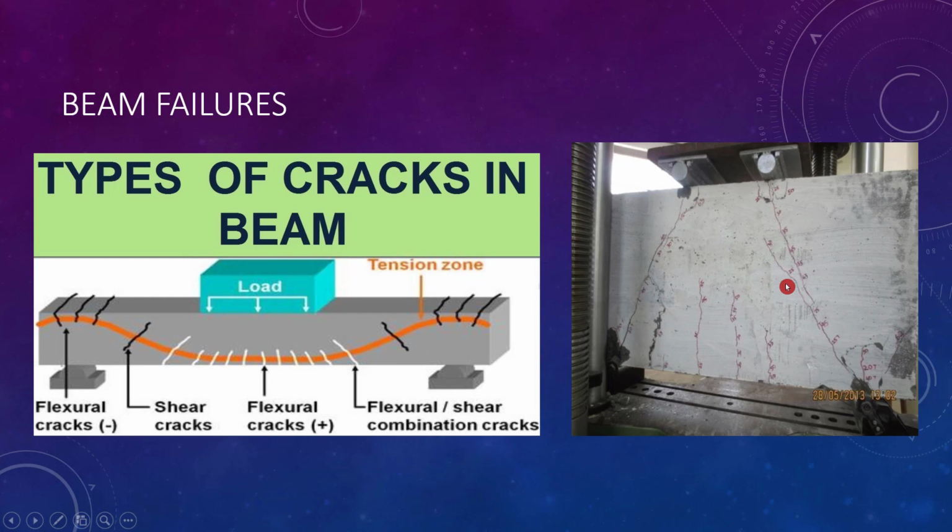On the right hand side, I have placed the figure of a deep beam. So you can see that the length of the beam is very small compared to the depth of the beam. So this makes, as I told, these beams very resistant to bending, and the behavior under the action of loads will be very different from the normal beam. So here comes the strut and tie philosophy, where under the action of the loads on the beam, there will be some formation of,